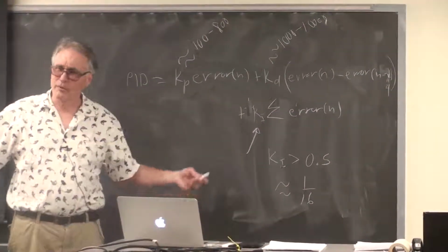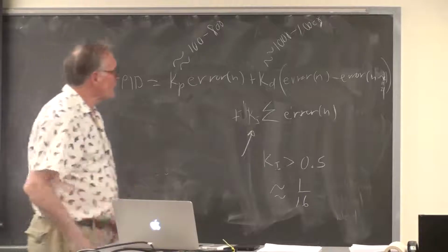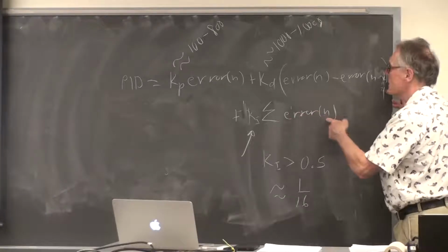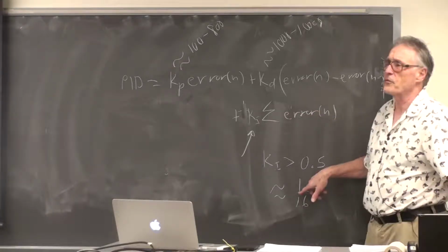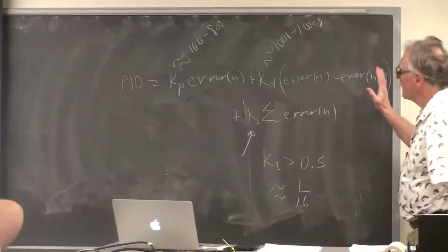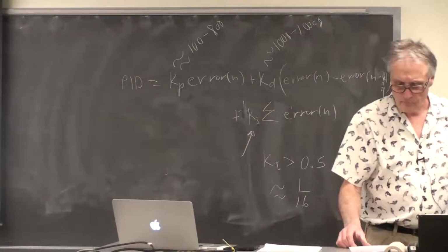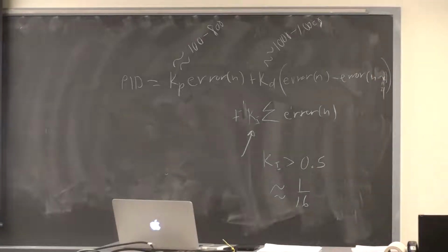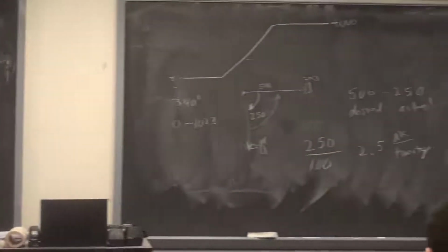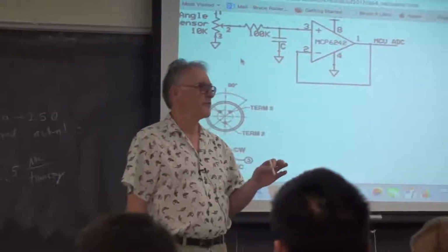Oh, damn! Now we need fractions. Well, you can just use a shifter. Exactly. Thank you. So instead of doing any kind of fractional arithmetic, you just take the sum of the errors and you shift them 4 bits or 3 bits or however many bits you want. So it's all integer arithmetic and a couple of shifts. So you can code this up with high-speed arithmetic quite easily, which means you probably could make the interrupt service routine run faster than a millisecond.